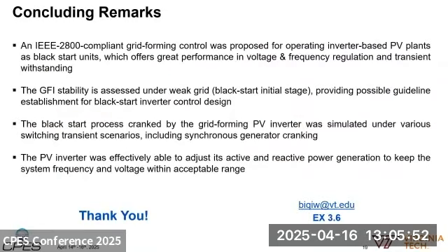So these are the concluding remarks. We propose an IEEE 2800 compliant grid forming control. It can operate inverter-based PV plants as black start units, and it offers great performance in both voltage and frequency regulation, and also a great transient withstanding capability.